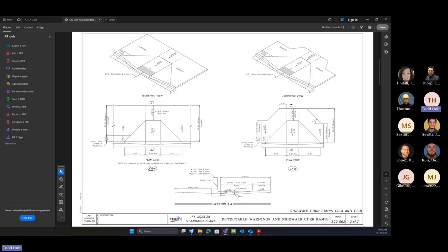if we look at the CRA or CRB, there's not much that varies between these, besides the sidewalk back and the landing. So maybe I want to come in and have this ruled and build in these modifications to that civil cell. So I can place it maybe as curb ramp A, and then configure it for a curb ramp B, or I have a curb ramp B, maybe transition it to the A, based off the references and the rules that we have in there.